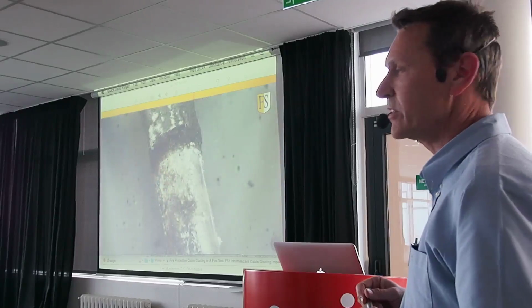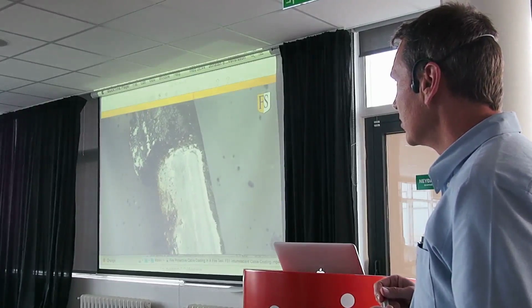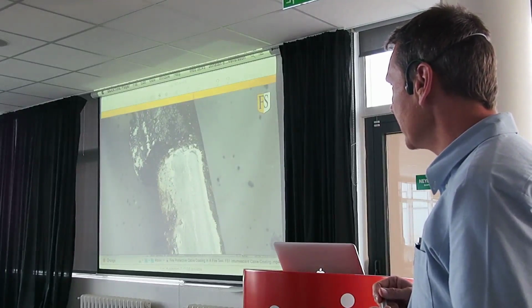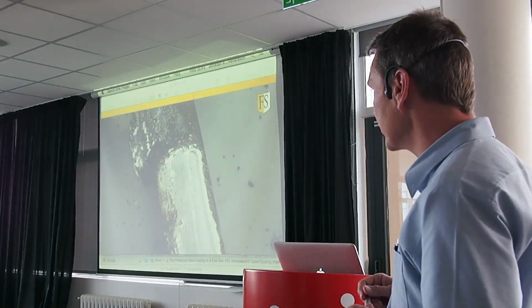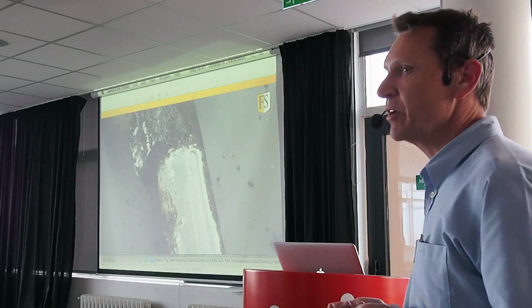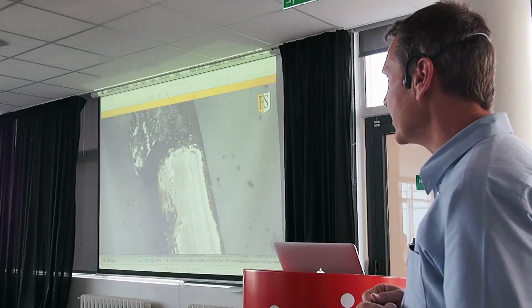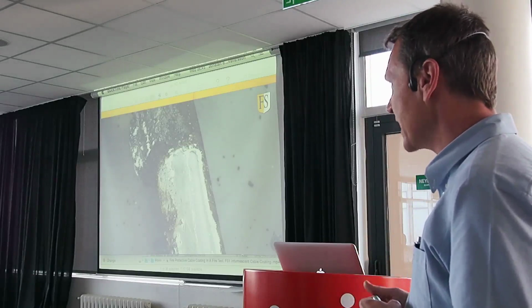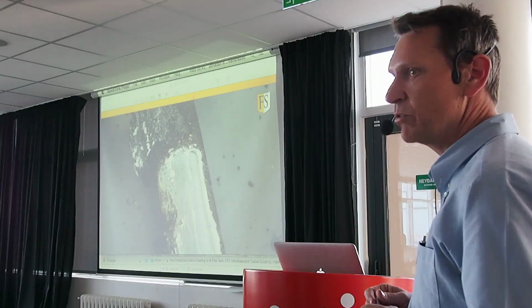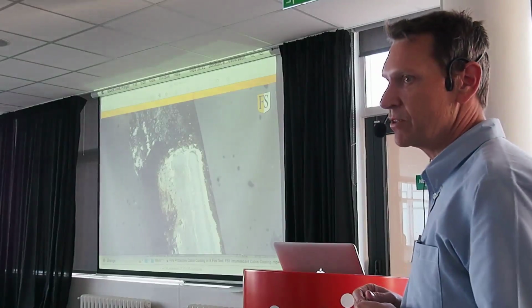Luckily, there's no talking in this video. So you'll see the expansion there. You'll see that the actual dry film thickness is only 1 millimeter. This runs for a 90-minute period. It's a 90-minute test. So we can fire rate a non-fire rated standard PVC cable for up to 90 minutes, whether it's a single or it's in a bundle or it's in a tray.